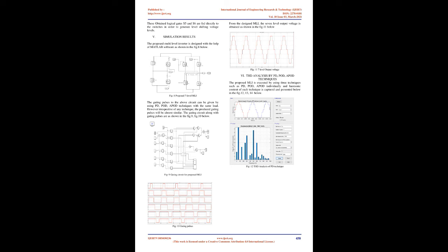By taking conventional BCD binary coded representation as reference, different pulse patterns for 6 triangular carrier signals and different available switches in the proposed circuit such as S1, S2, S3, S4, S5, S6 are tabulated clearly in the below table 2. In order to design the logical gated sequence for switch S5, consider one full cycle for the purpose of analysis. The time period of the modulating sinusoidal signal for one full cycle is 0.02 seconds, whereas the carrier signal frequency is chosen as 2 kHz.